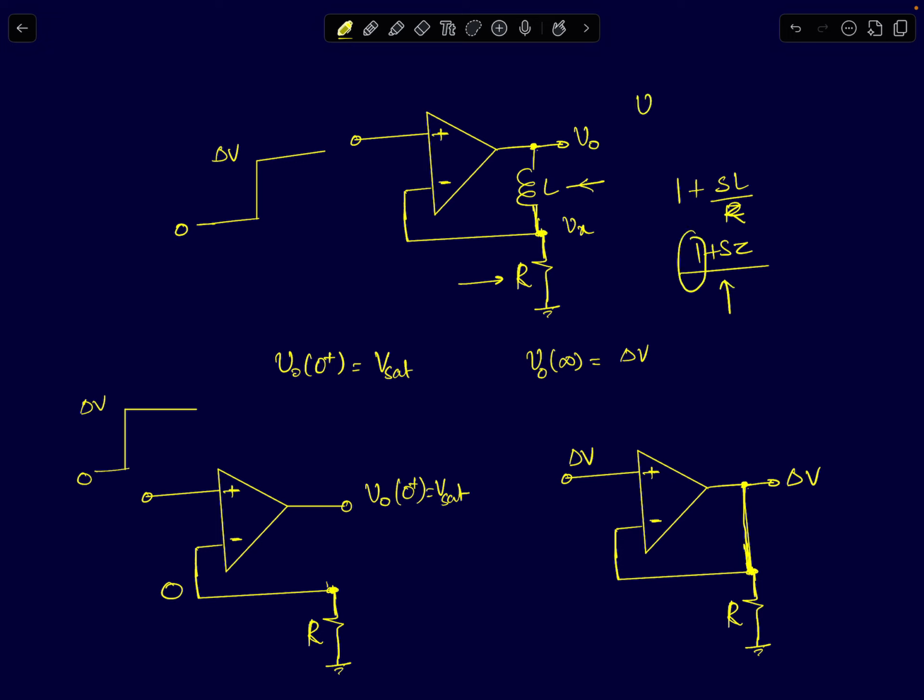This is the transfer function written in the Laplace domain. In the time domain, the output voltage will be given by V_o(t) = Vi(t) + tau dVi/dt. This will be the expression for the output voltage. This part contains the differentiator information. This part is the proportional path. It just has a proportional component, which is just like a voltage follower. So it follows the input voltage and also performs this differentiation.